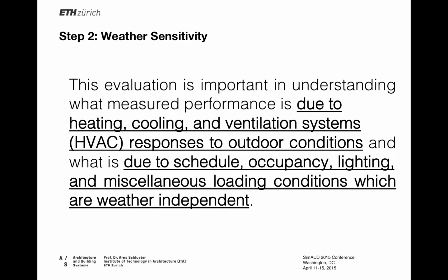So the second step we call weather sensitivity screening, and this is meant to tease out or understand or quantify the correlation between the performance meter and outside air conditions, to distinguish between meters that are measuring equipment which is correlated with either heating or cooling. And if it's not, it's weather independent, it's probably due to occupancy, lighting, and other loads which are not weather dependent.